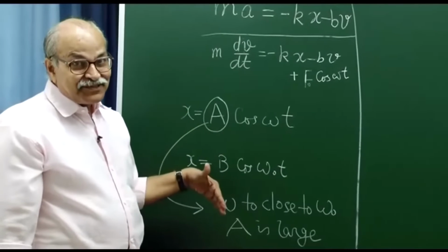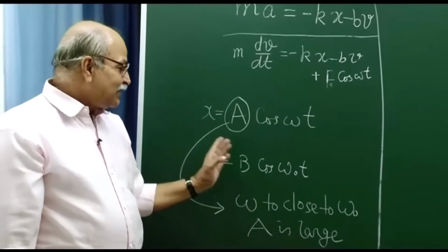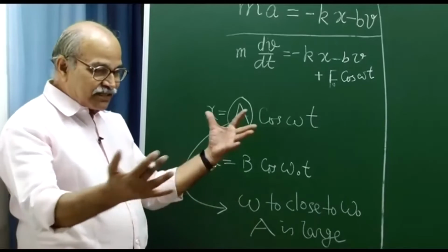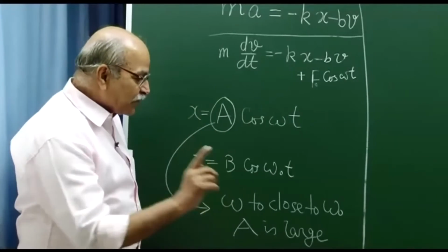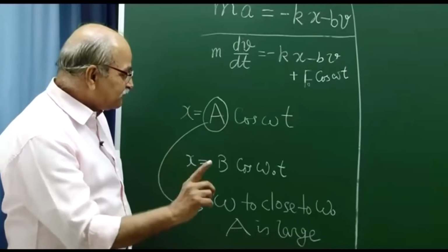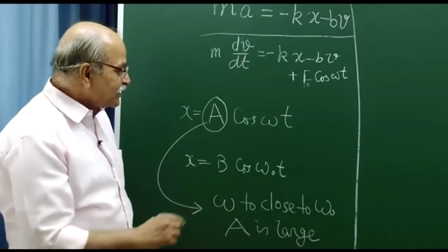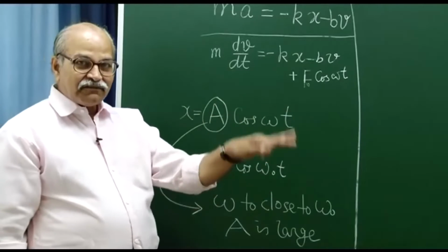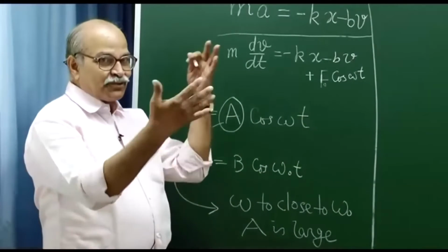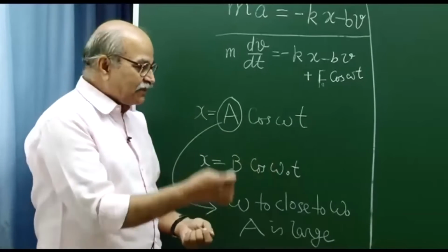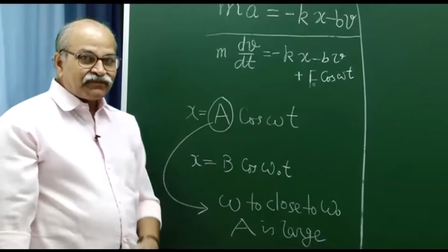This phenomenon is known as resonance. When these frequencies match, you have large amplitudes. That is what I was doing. I was trying to adjust the frequency of the displacement of my finger to the natural frequency of that straw system, and if that happened, the amplitude was large, and if this frequency was very low or very high, the amplitude was small.